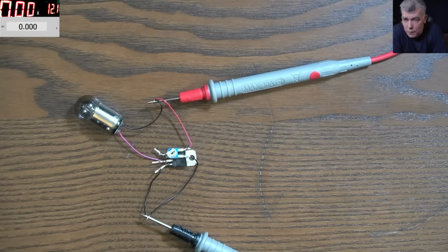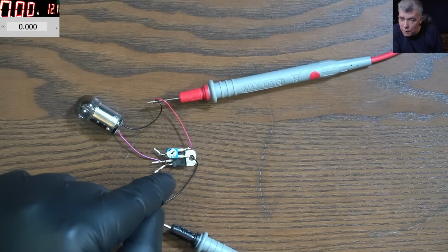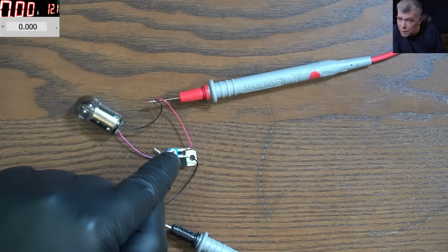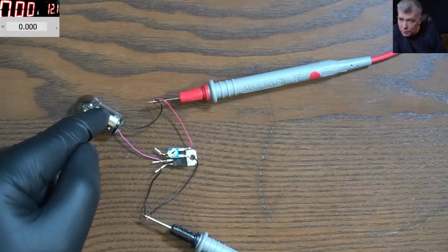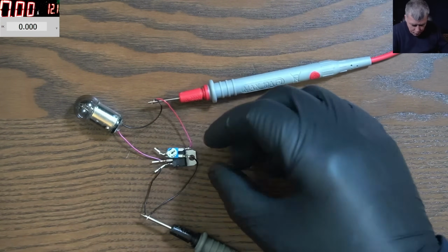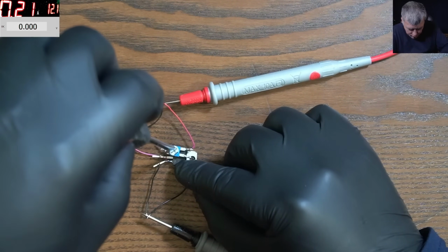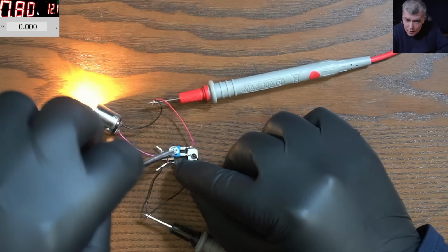What I want you to understand is that just by triggering the transistor only from the base, with a small current, actually microamps, we can drive a light bulb which is taking a lot more power. Like on this one, let's see on the power supply, this light bulb is taking 800 milliamps, you can see.